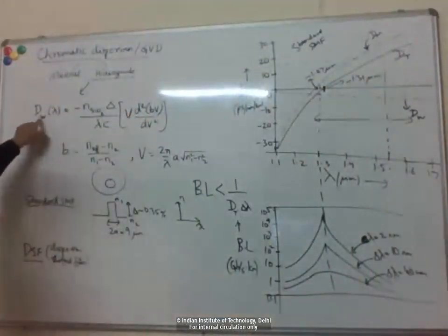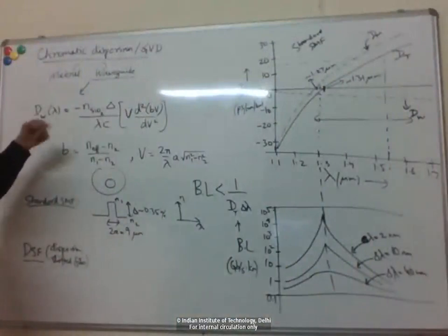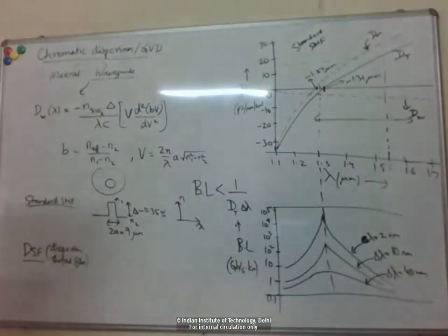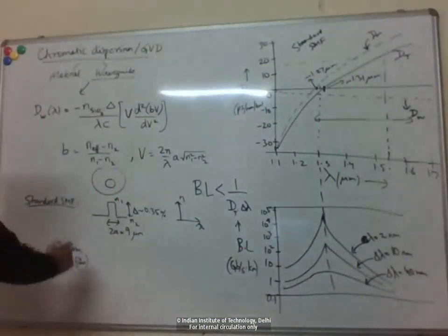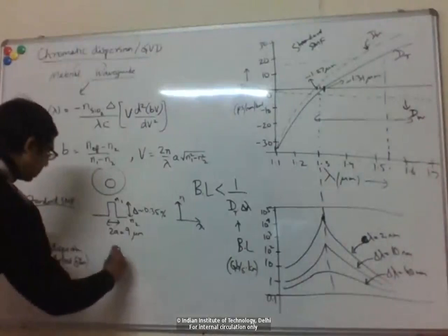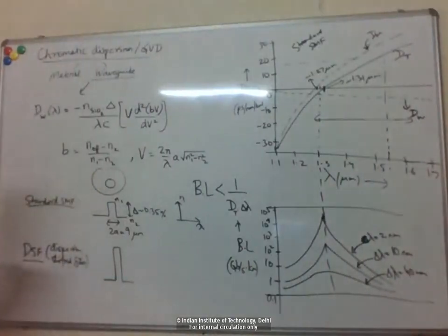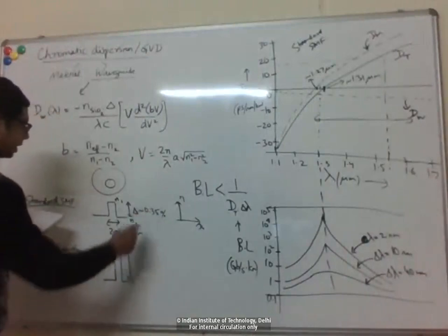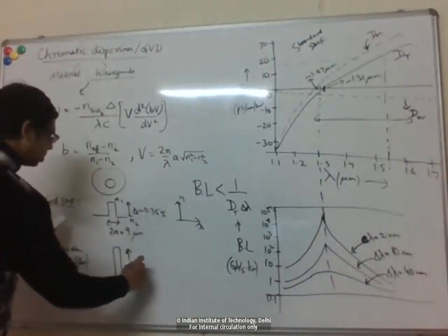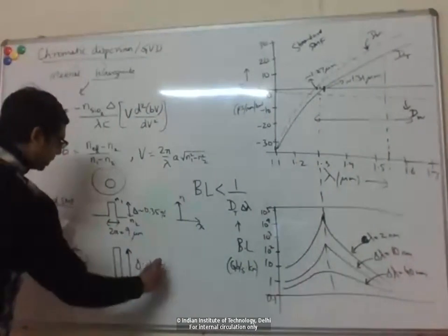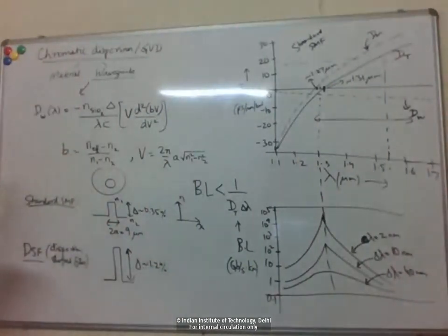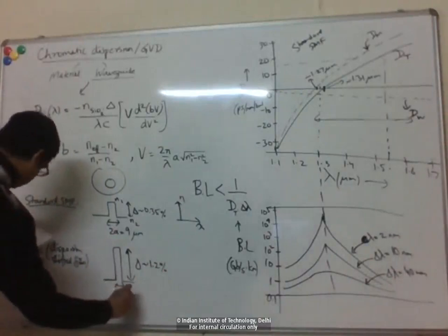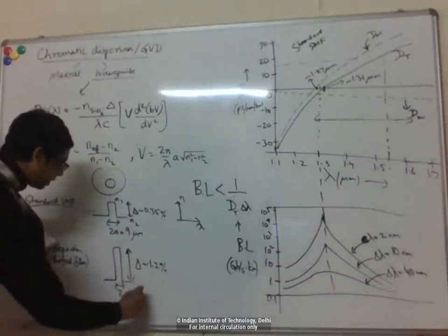I can make the waveguide dispersion more negative by increasing this quantity delta. This dispersion shifted fiber basically increases the core cladding index contrast. You increase this by roughly 4 times, so you go to about 1.2%. Also, the core size is decreased a little bit, or roughly halved.